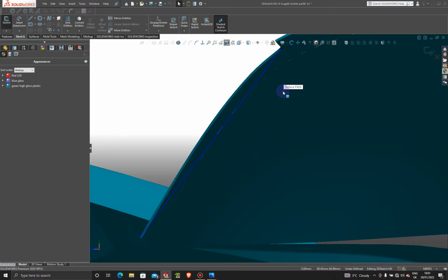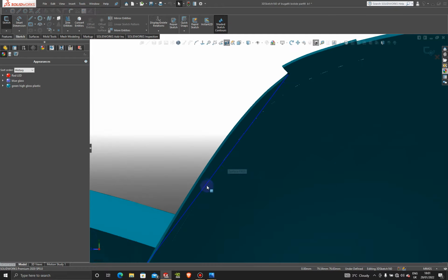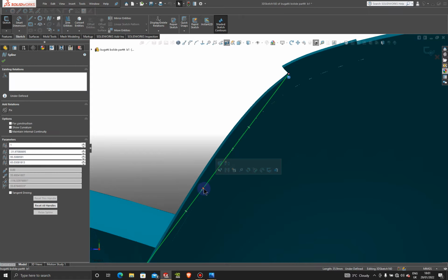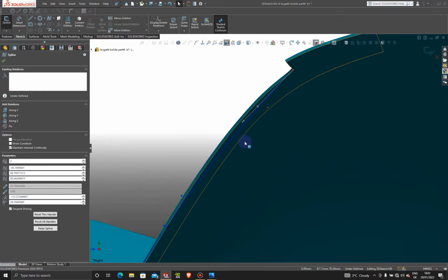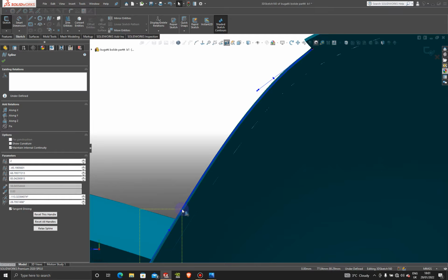All right, so what I want to do is create this curvature to fall somewhere in the middle of this body here. So let's click on this line, and let's just adjust this so that it falls somewhere in the middle. And then just remember that this curvature will actually give the profile of our side window, so we've got to be careful with the adjustments that we make.